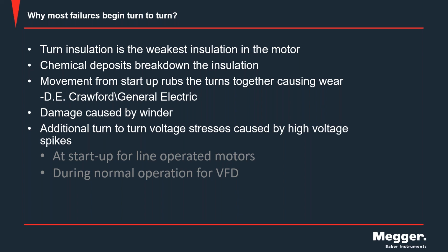Chemical deposits break down the insulation. All that list of stuff we went through, those two slides, work on that insulation. Movement from the startup rubs the turns together, causing wear and damage caused by the winder. And additional turn-to-turn voltage stresses caused by high voltage spikes. Startup for the line operated motors, during normal operations for VFD. As the VFD, the variable frequency drives, switch, it's causing these voltage spikes in that motor.